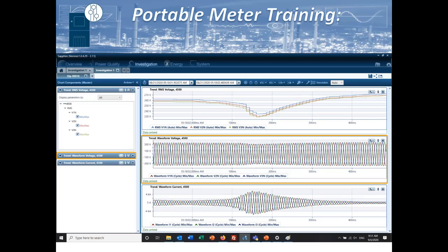At this point, I can also add or take away time just with a couple of clicks of buttons. So I can add a second before the event, 2 seconds, a minute, an hour. So if there's something that's been cascading over the past hour or building, I can, from this one event, add time to and from both ends and expand that out from a couple of cycles to well over an hour worth of continuous data. So that kind of gives you an example of how the power quality works as well.